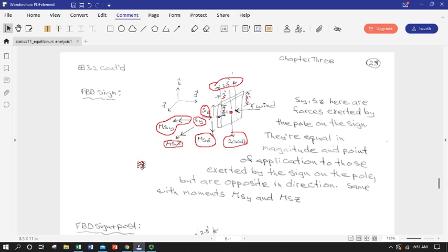Or at least we're pretty sure it does. And if it doesn't, we'll solve for equations of equilibrium and find that to be 0. Okay. So to recap, this is our FBD. Basically, we've had to assume that the post is going to have to exert a force in two directions, z and y, and it's going to have to apply a moment in the y, the x, and the z. So a fairly constrained support is coming from the post.